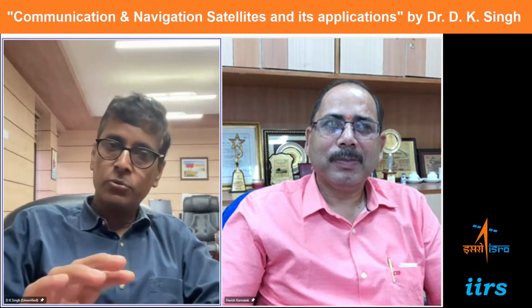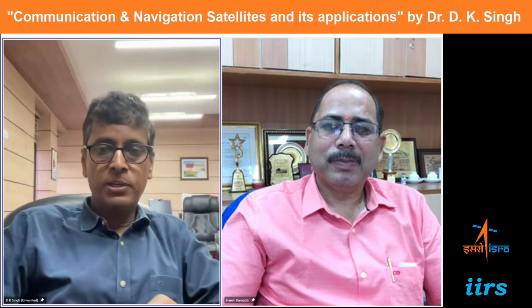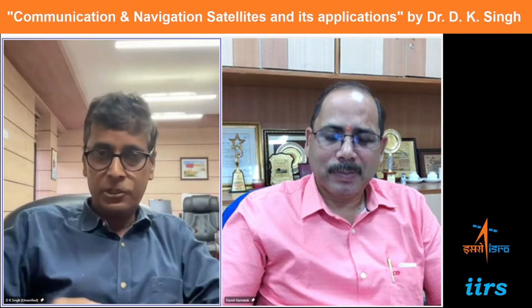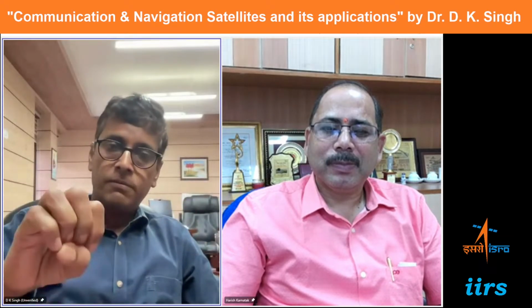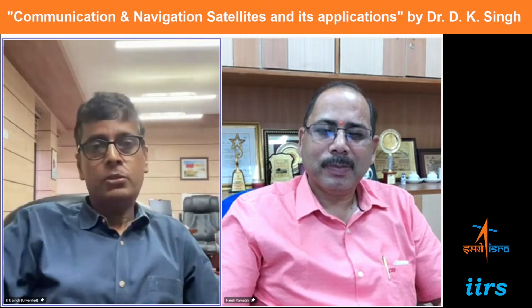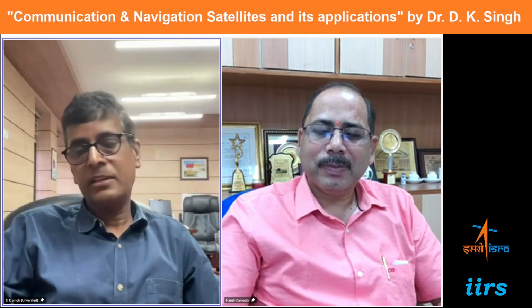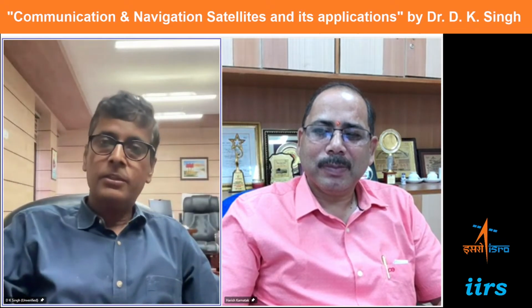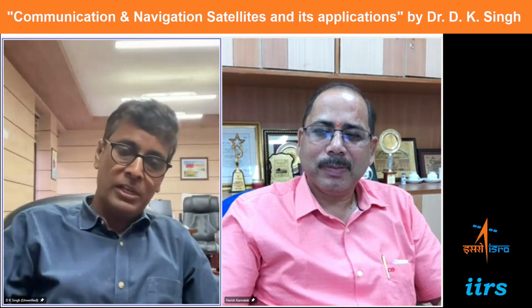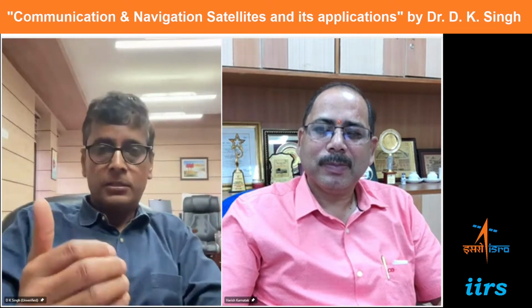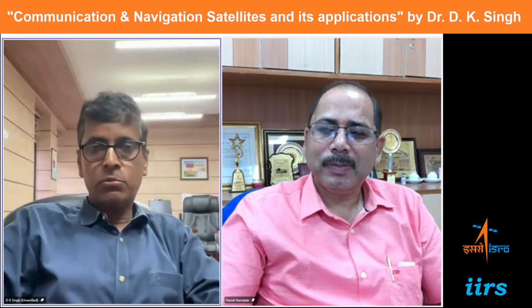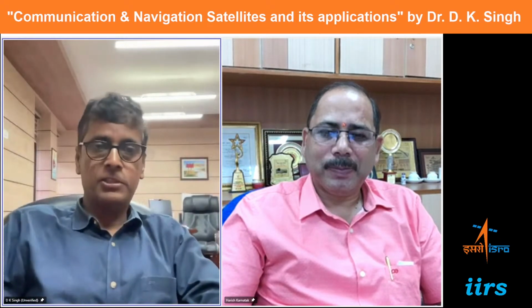Second, the other thing is GEO satellites are not able to cover the polar region. So they are confined to plus or minus 70-degree latitudes. So a full-fledged satellite communication system leverages the strengths of LEO, MEO and GEO. So LEO and MEO satellites can provide the coverage in the polar region also. Another important thing is, everybody knows, because of the relative motion we have Doppler frequency shift.